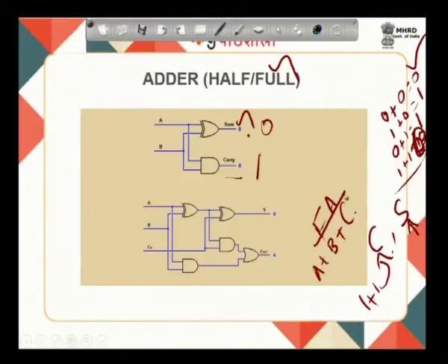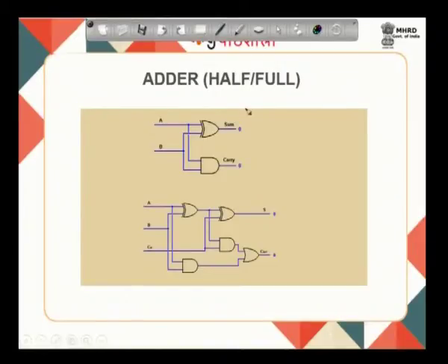There also you just see that when you are looking at A plus B, I will be in a position to add these two numbers, I will be getting a result over here, and when I am looking at the third value also I wanted to add it, I am going for a full adder. So, when I am looking at a full adder, I will be looking at two half adders combined together. So, A plus B plus C, which will be two XORs added together, I will be getting a sum. Whereas, I am taking A and B added together to get a carry, and again this carry is also added together.